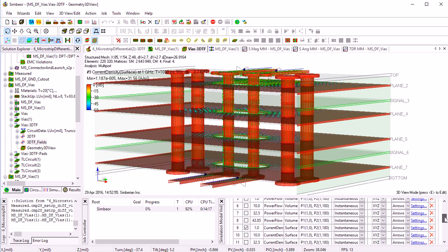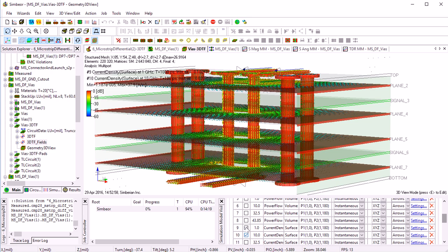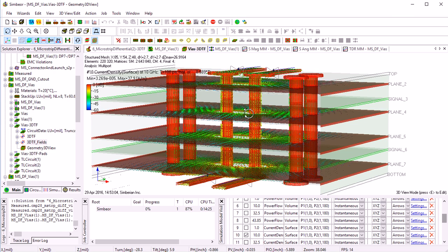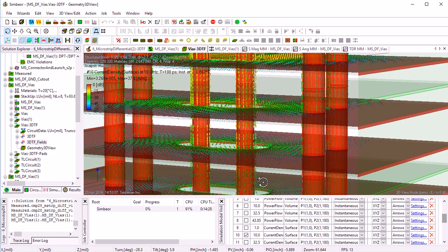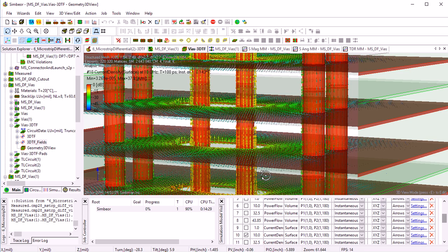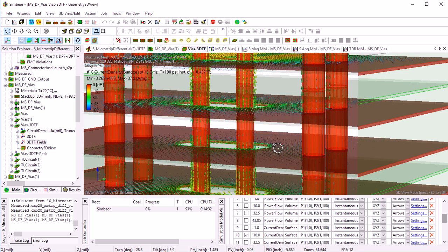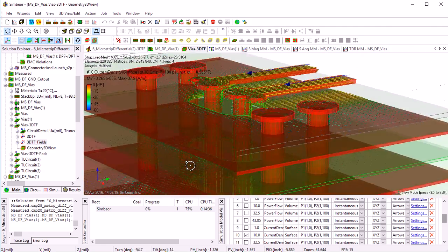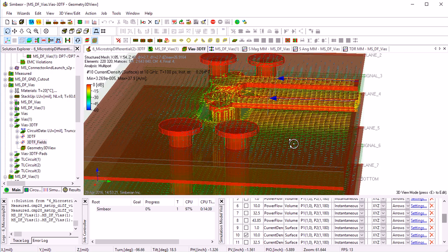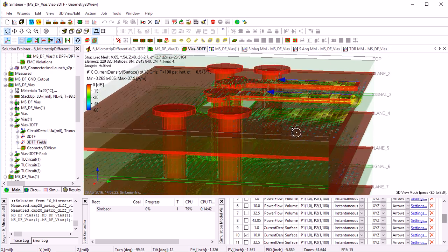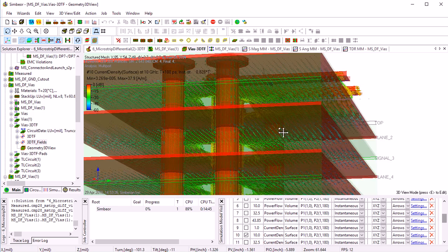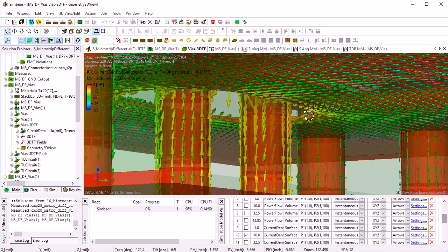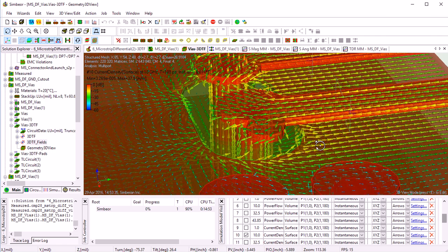Current density at 10 GHz. There is not much change, except that now we can see kind of wave-like behavior. It works almost as a transmission line. More currents flowing on stitching vias. And again, currents are perfectly kind of one direction, another direction. Then return current flow on top. Right here we see the distribution of the currents on the planes, and some current gets back through the stitching vias.